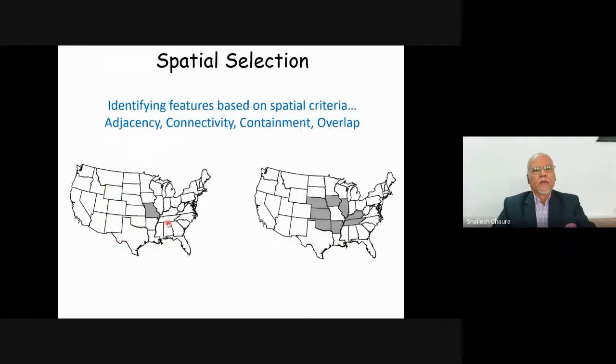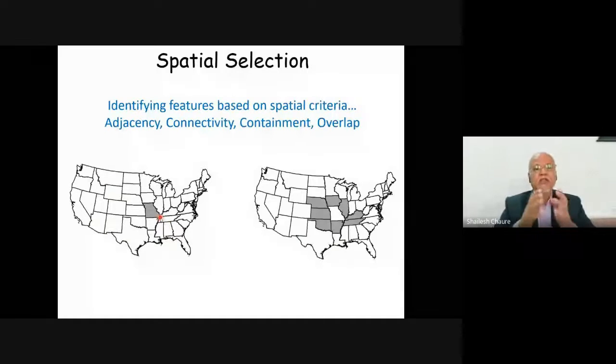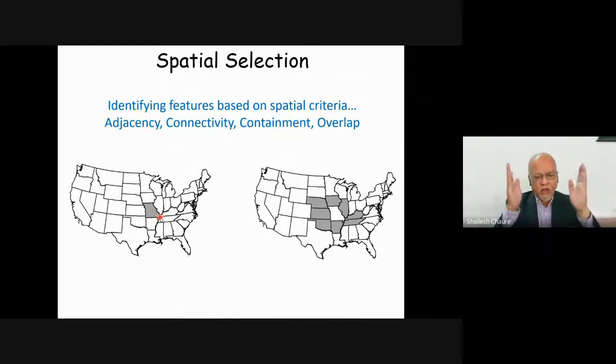So, spatial selection. Selection means that out of the huge data, you will select something. That is as simple as that. Spatial selection means selection based on location. Like in filtering, you select where the area is greater than some value. If you have 10 polygons in your data and you write a query that filters area greater than this, then only those rows fulfilling that condition will be returned. This kind of filter or query is an attribute thing.